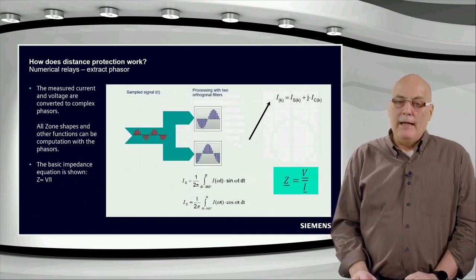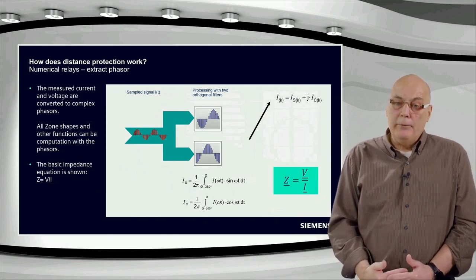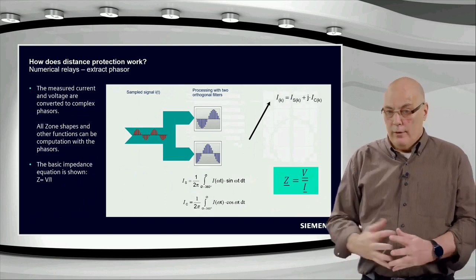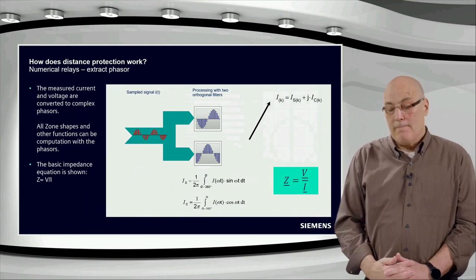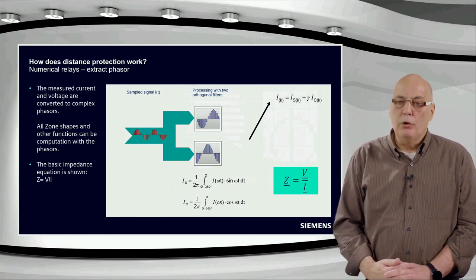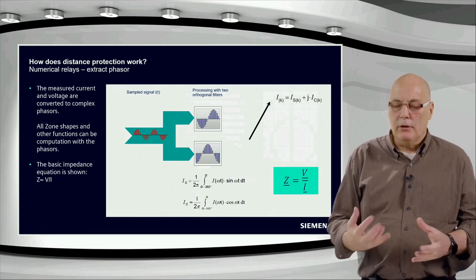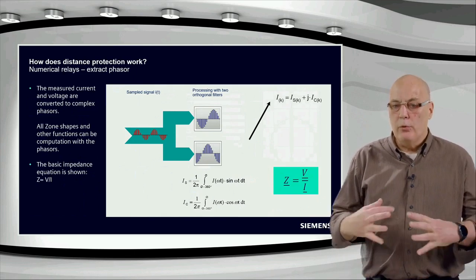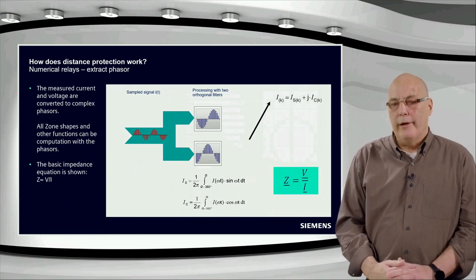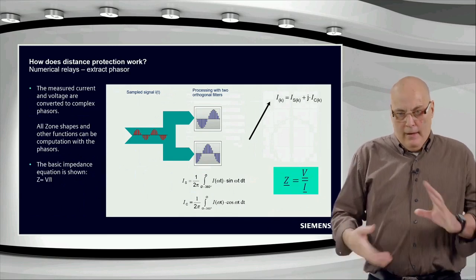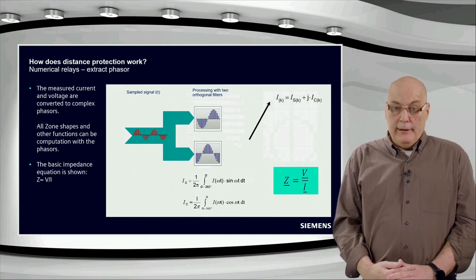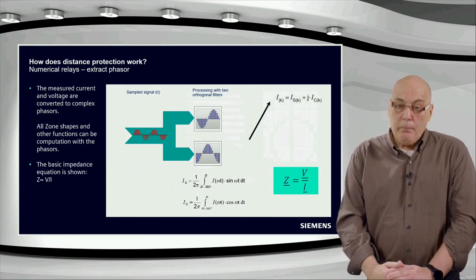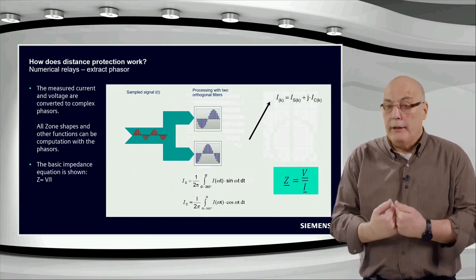And that is not really that helpful yet, because you can work with sampled value algorithms, normally not preferred, because you prefer to run this through a filter, because the filter will take away some disturbances and so on, and smooth out and reduce your error susceptibility. And then one combines this filtering technique immediately also with extracting what we need, and that is the phasor.